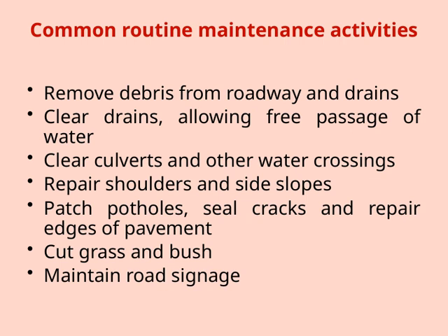Clearing drains ensures that water can flow freely, which is vital for preventing flooding and damage. Similarly, clearing culverts and other water crossings helps maintain proper drainage and avoid backups that could compromise the roadway. Repairing shoulders and side slopes is also important. They support the pavement and help prevent erosion.